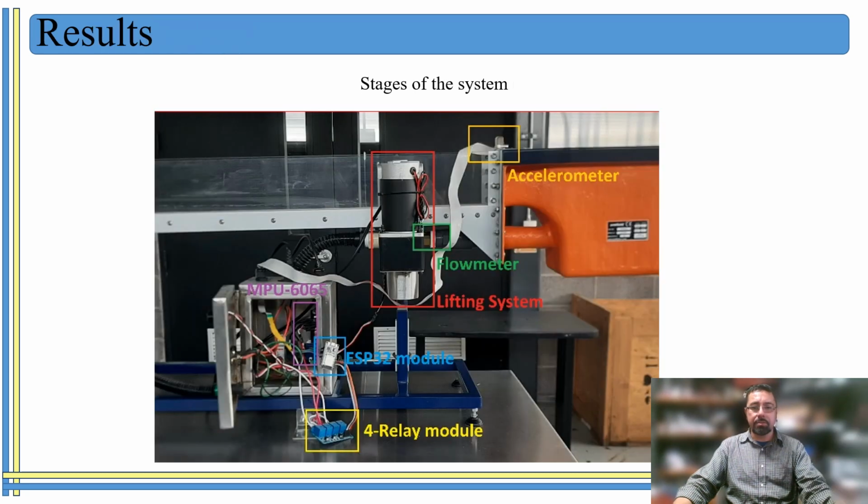These are the stages of the update implemented on the old and basic configuration water canal. For example, you can see the DC motor. It's a 90 volts DC motor, and the water tank, where the gyroscope is connected in order to measure the slope or inclination of the water tank and the water canal.